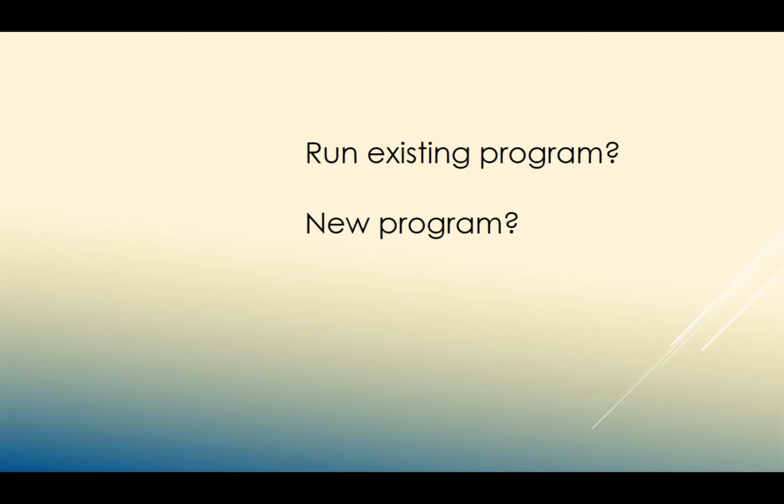And it does it with a bit of software that sits already inside the Nano, the bootloader. So the bootloader's job is to say, keep looking for a short time at the incoming stream of serial coming in from the USB. And if nothing's coming in after a certain amount of time, you're not trying to program it, in which case you can run the existing program. If you detect signals coming in the serial, then you know they're going to overwrite any existing program with new code.